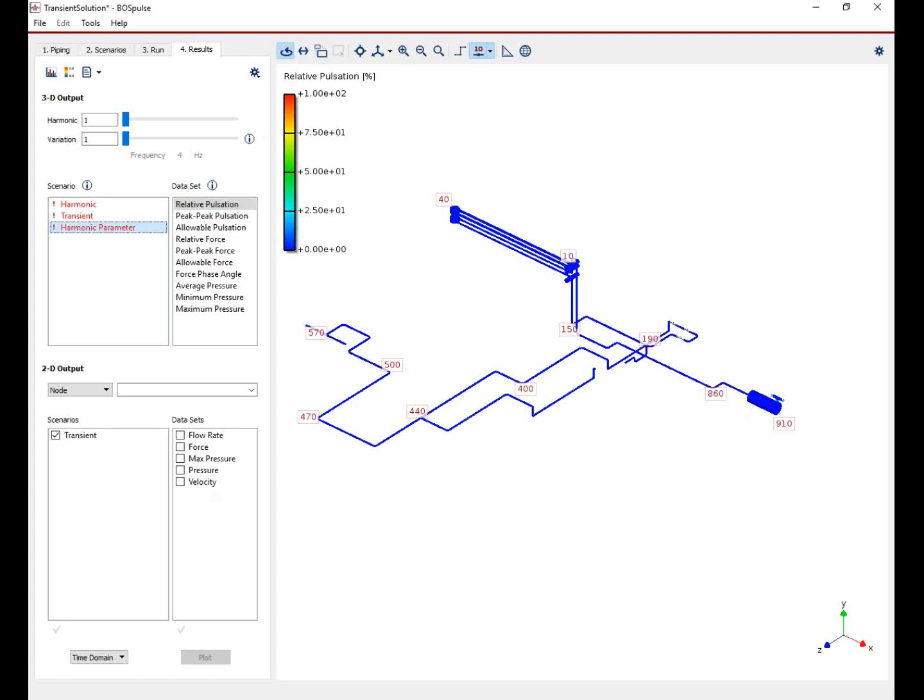But most often, only changing the RPM will resolve it in that case, if you already have built the system. Regarding pulsations, you can also place an orifice at some location. It does increase the power of your compressor, but if you place it at the correct location, you can effectively break that acoustic mode and reduce the initial shaking forces to start with.